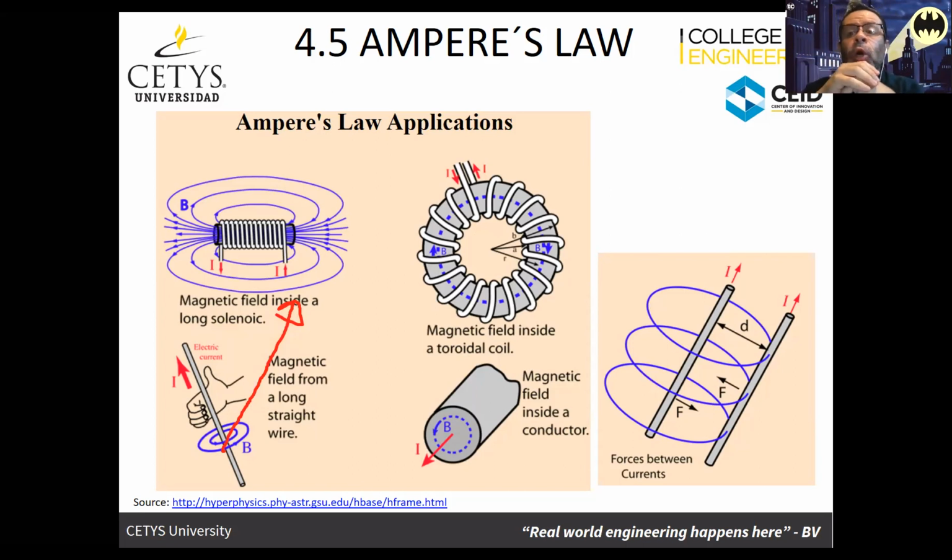Remember that we talked about that. Well, kind of the same principle applies here. So we're talking about the magnetic field. The strength of the magnetic field is going to be proportional to the length of the cable and the current going through it. So for a given current, we would need a very long cable to have a strong magnetic field. So what do we do to make a very long cable or a very long length? What do we do to make it compacted? Well, we roll it up. And that's the concept of a coil.